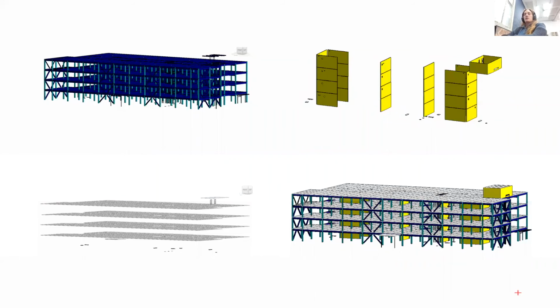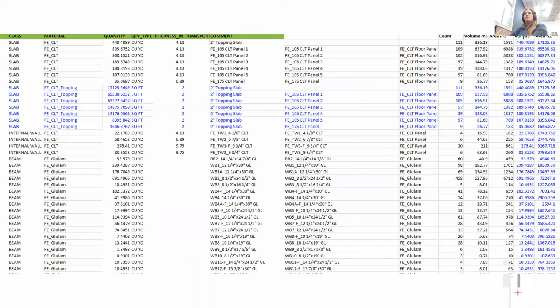And the way we're doing this on an analysis level is we're assigning materials in Revit, separating groups of systems, and then pulling out that information in a tabular form to say, here's the quantity of material that we have in this building, and then trying to look at those numbers and understand the impacts of the decisions that we make.